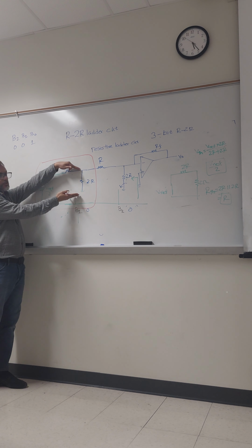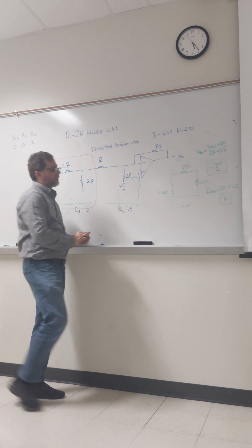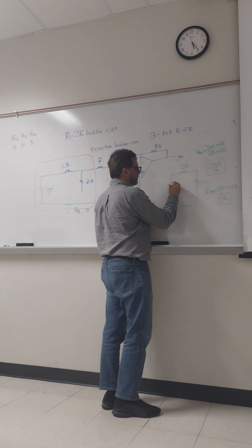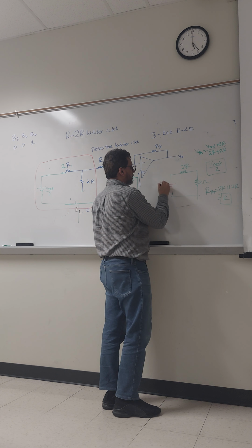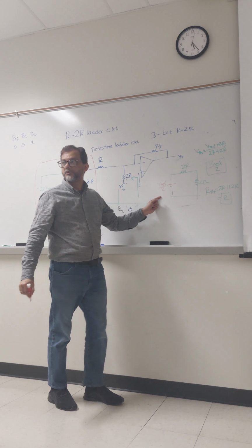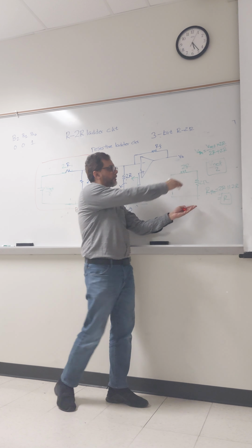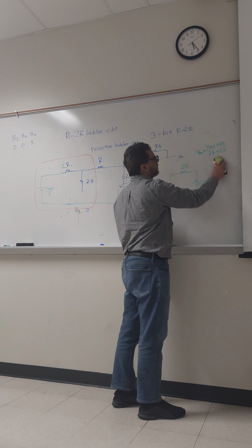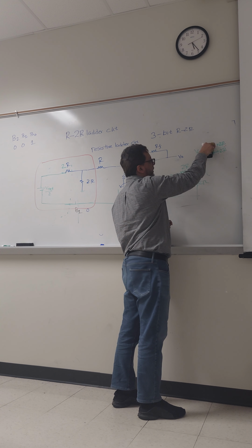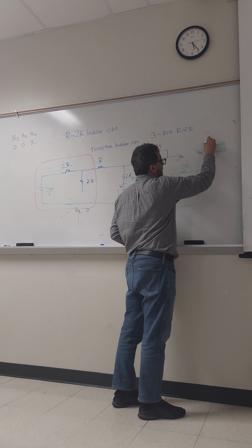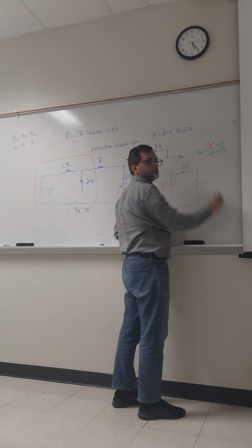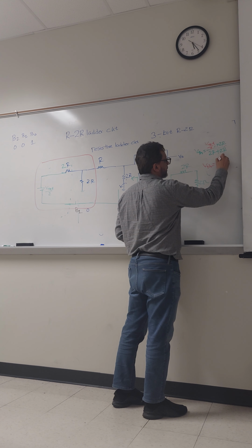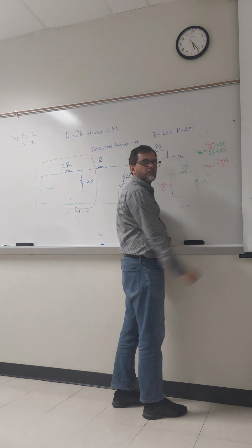You have to find out across this resistor. So now you have to apply again. So now my voltage is how much? The reference by 2, twice R. We have to find out across this one. Apply the voltage divider rule. So now instead of V reference by 2, V reference, we have V reference by 2. So we get how much? VTH? V reference by 4.